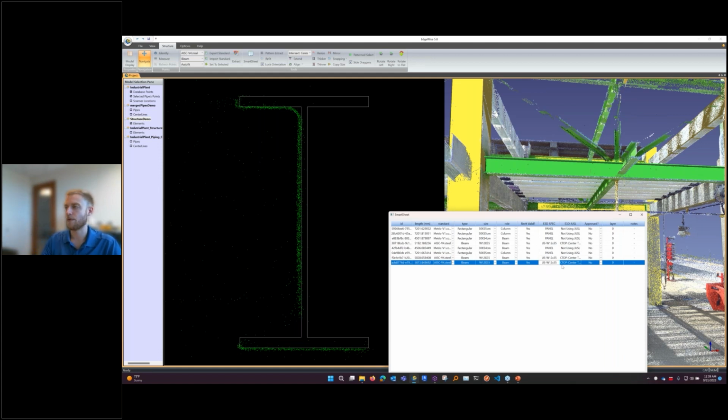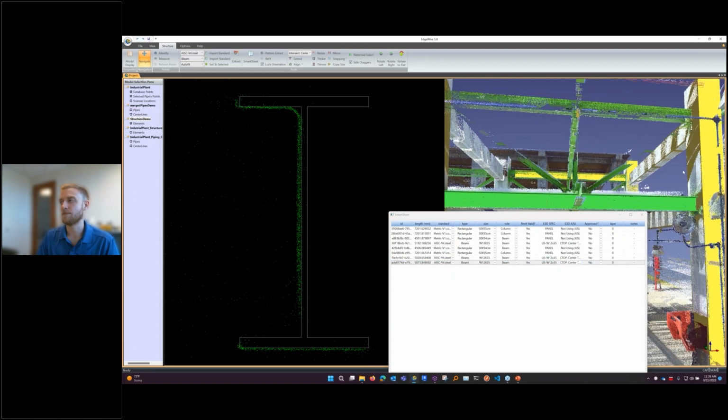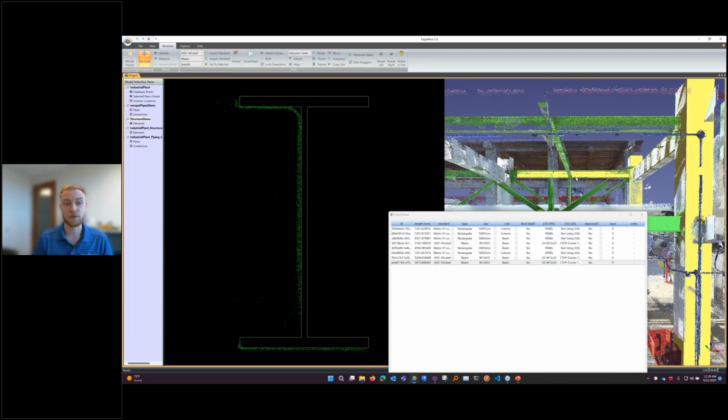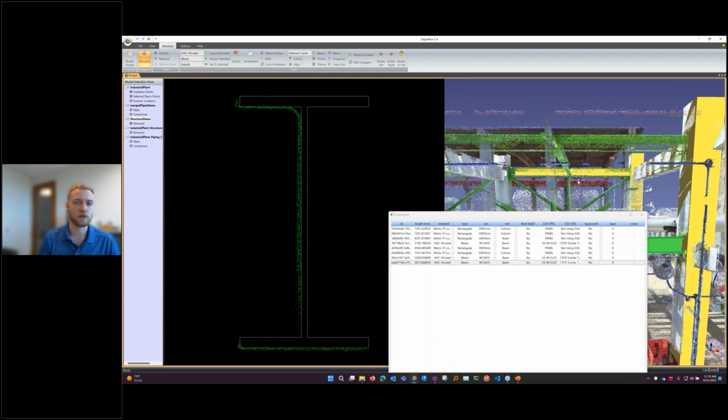file definition. And the other thing we're doing is we have the C-top, so we are defining justification to make sure that we put things in the right place, and then we set it. So if it's an I-beam and it is a beam, we're going to do center top. If I make an angle a column, a vertical column will be center middle, and if I do angle iron, it'll do different ones. But we try to add the logic here to make sure that when it goes into E3D, it's in the right position and kind of defined correctly for the easiest usage.